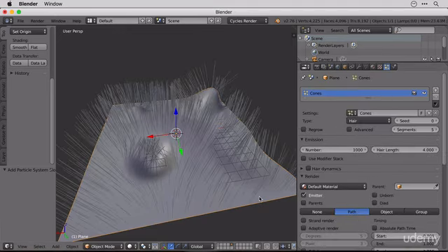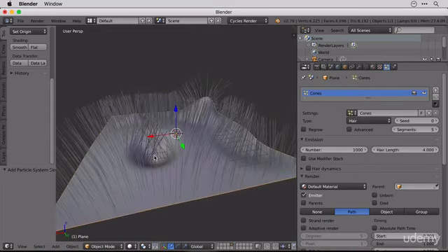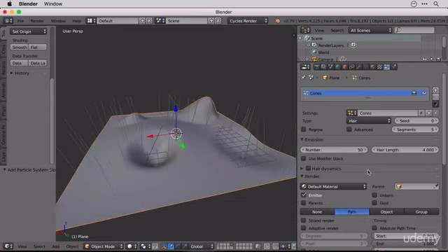It's going to be of type hairs, and we can see the hairs are now growing out. Now we can replace those hairs with objects. Now I know with the size of cube I'm probably going to have to turn down the number that we have, so I'm just going to turn it down to maybe 50 for the moment, and that also keeps our viewport nice and quick. We can always change this later.